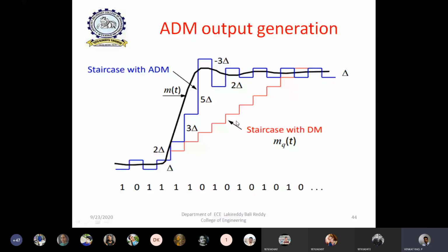If you apply this signal to delta modulation, based on the two-level delta modulation quantizer, it will approximate the staircase waveform like this. It only increments by the fixed value of the step size. Even though the input suddenly rises, it cannot follow up to this level because the height is fixed. It will increase only up to this step size height.